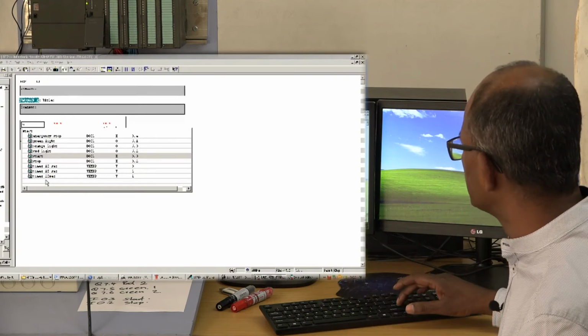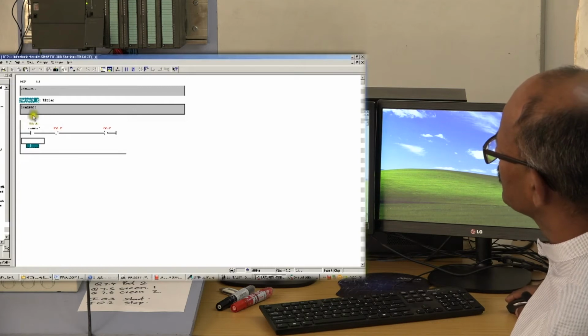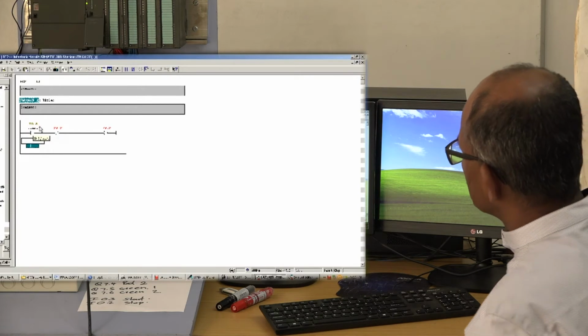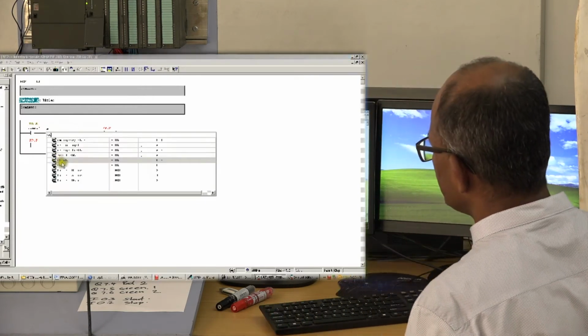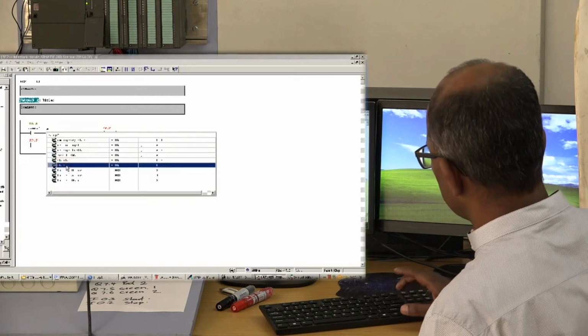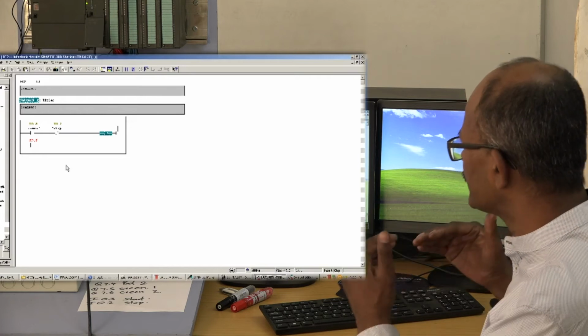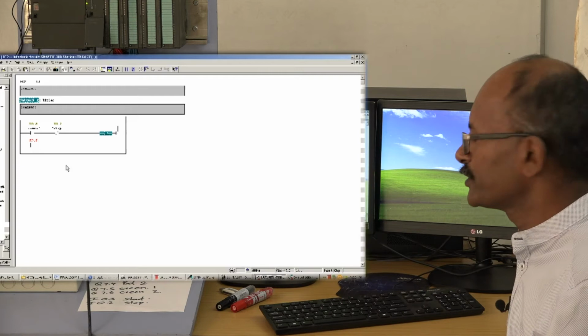I just have to hit enter. And you see it comes up as I0.3, and that is my actual start address. If I want to go to stop, if I type in ST again, there's my stop button, click on it, hit enter twice, and the stop and the address comes up.